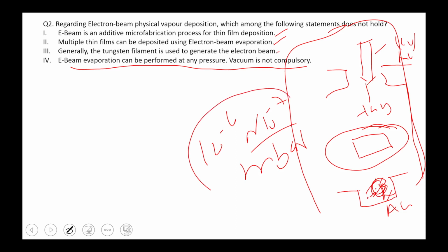So that pressure is 10 to the power minus 6, 10 to the power minus 7, in the vacuum, like in space. The pressure is low, so the material will evaporate and be deposited, with ions striking the film. And the substrate will rotate, so uniformity will be better, because it rotates uniformly and ions strike the surface of the substrate.